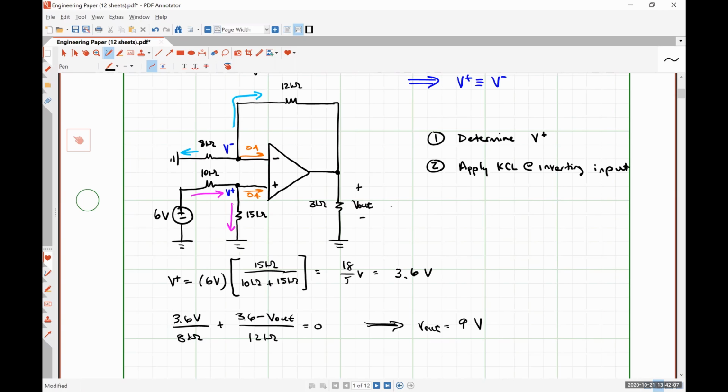The only time it would is if it were 0. So if you short out the output, then obviously the output voltage is going to be 0. But other than that, the output resistance doesn't particularly matter. Now in a practical op-amp circuit, meaning a physically realized op-amp circuit, that's not remotely true, but we're just looking at an idealized case here.